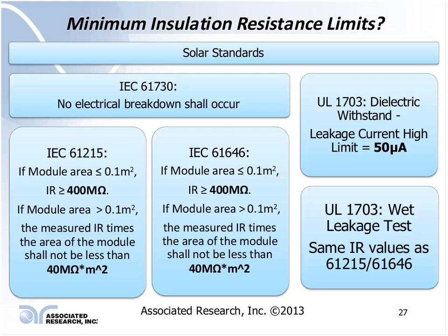And if you're talking the megaohm range, with a voltage of 1,000 volts or more, you're still talking sub-amp here. You're talking milliamp to microamp range of leakage currents. So it's important to remember that we're still dealing with very small current values when we're talking about these high resistance values. You could do a simple Ohm's law calculation to figure it out. You really are going very small current values, and this makes sense. The smaller the current, the better. Somebody walks up and touches this thing, we want them to either barely perceive this current. We don't want it at dangerous levels. So this is where some of those limits come into play.